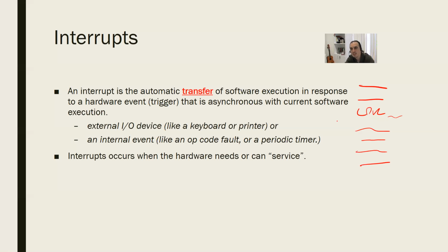At some point, an interrupt comes, you stop running this code and you jump to another line of code. When this trigger will come, you don't know because it's not written in the code. It is coming from outside. Somebody has pushed the switch or a packet came. And while this packet came, you were not waiting busily for that packet or that switch.